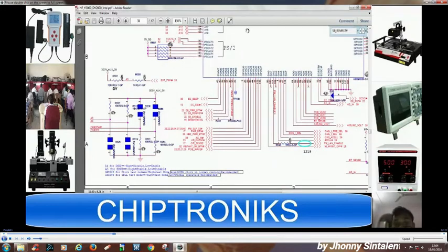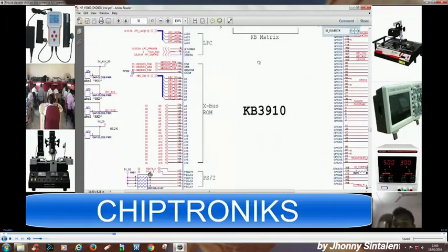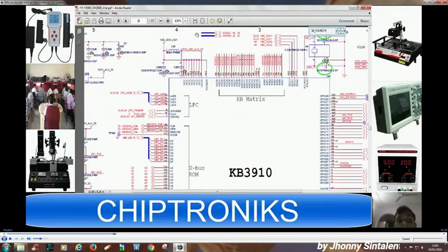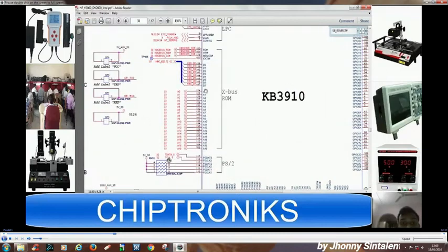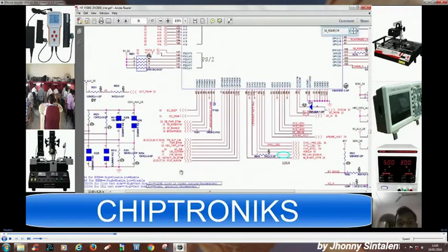Now when will this come? It will come when the EC inside the IO controller gets power, that is, this IO controller gets supply, reset and clock, and this EC can read the EC BIOS via the BIOS interface. So we had already checked all these things, and when this IO controller receives the power button signal, you can see KBC power button. When we press the power button, then SB underscore RSM reset will come. We'll see from where this power button signal is coming.